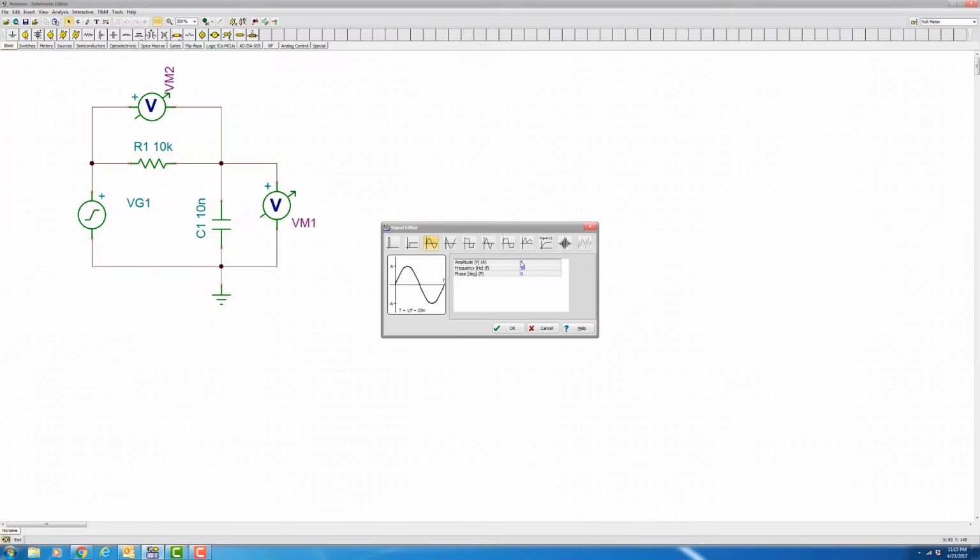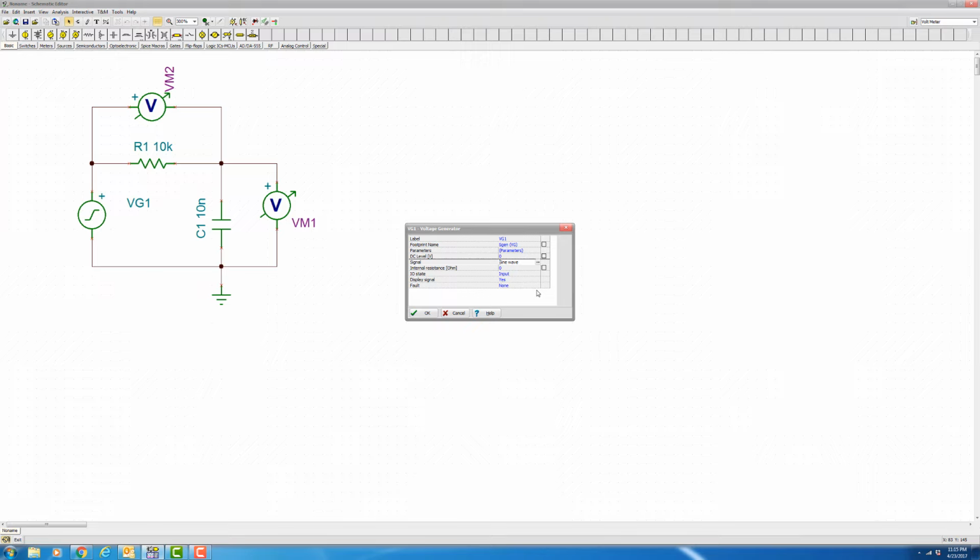So that it says amplitude of 1. That's not 1 volt peak to peak. That's 2 volts peak to peak, where the half amplitude is 1. So that's annoying, but that's the way SPICE goes. There's also things for phase and frequency, but we're going to put those into the sweep menu, which we'll see in just a second. Click OK.